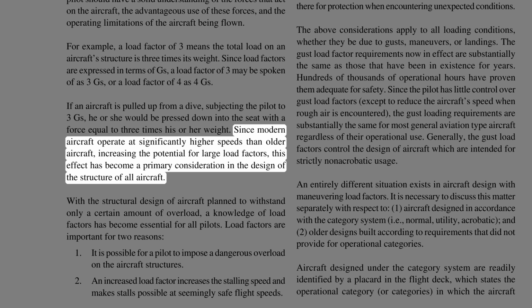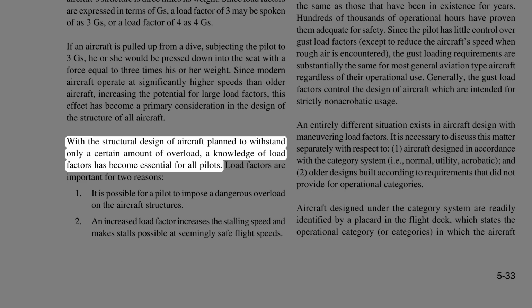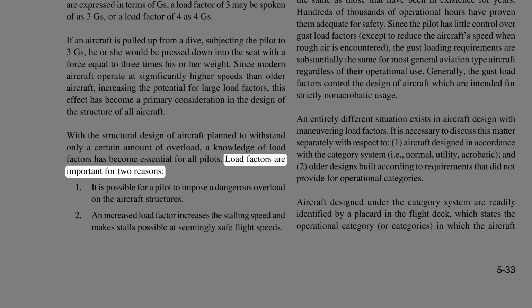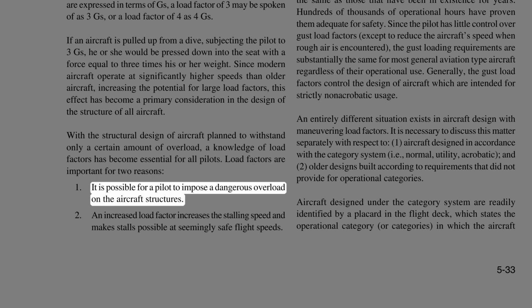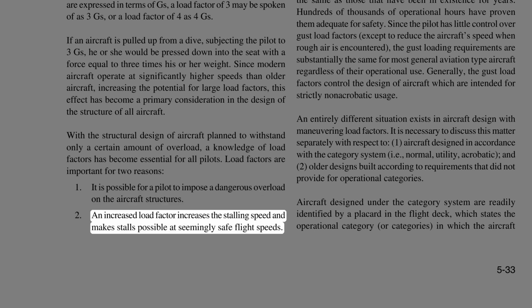Since modern aircraft operate at significantly higher speeds than older aircraft, increasing the potential for large load factors, this effect has become a primary consideration in the design of the structure of all aircraft. With the structural design of aircraft planned to withstand only a certain amount of overload, a knowledge of load factors has become essential for all pilots. Load factors are important for 2 reasons. It is possible for a pilot to impose a dangerous overload on the aircraft structures. An increased load factor increases the stalling speed and makes stalls possible at seemingly safe flight speeds.